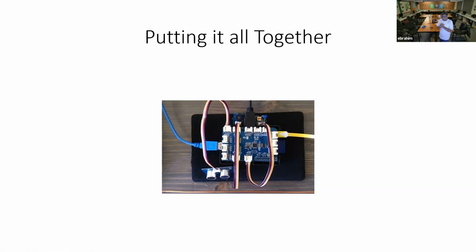When it determines that the humidity level has increased above a certain extent, what will it do? The microcontroller, this part here, sends a message to the actuator. What is the actuator? The motor that controls the arm for your wiper blade. What does it tell it? Come on. And you see the motor starts up and your wiper blade starts moving from left to right, right to left, clearing your windscreen.